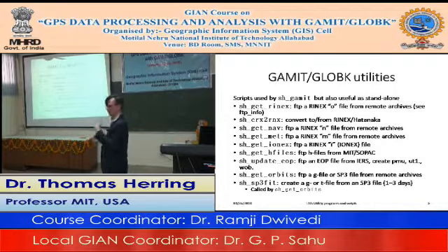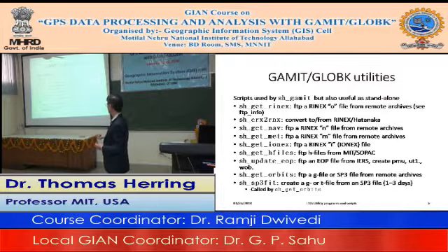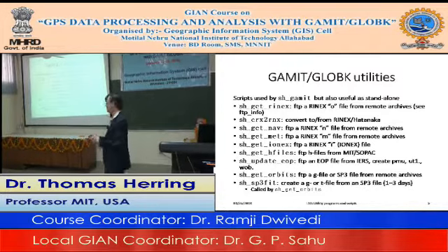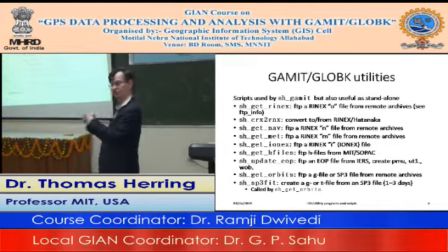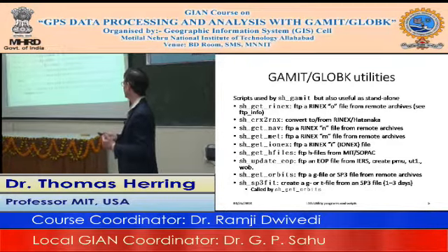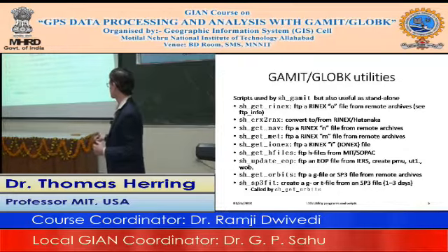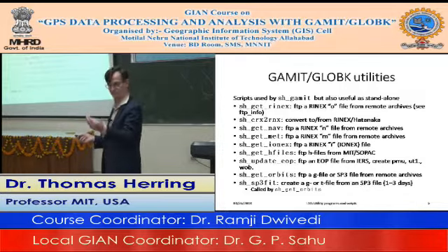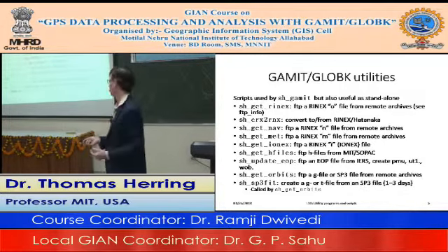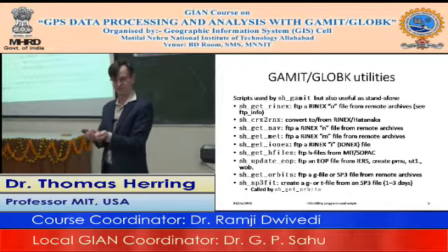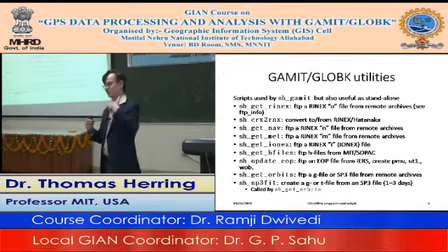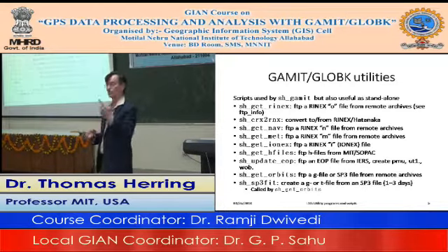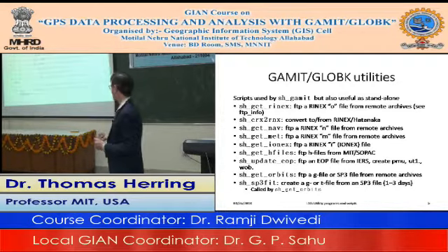SHUpdateEOP gets you new Earth orientation parameters. And again, SHGetOrbits is the shell script that goes off, gets the GPS high-precision orbits from the archives, and optionally converts them into the MIT format that we use for orbits. SP3fit is a way that you can convert Cartesian XYZ coordinates of an orbit and fit them to an orbit trajectory using the orbit integrator, to see how close that orbit is to something for which we know the dynamic forces. That's automatically used in SHGetOrbits.